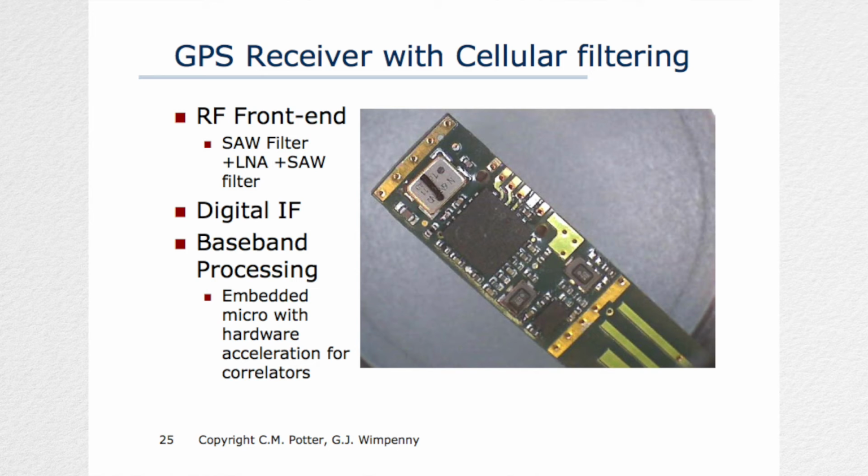There's a serial digital output there. So all of this takes RF in from the satellite and produces a location data stream coming out of it. It simplifies the design task of adding GPS functionality to anything, really. These are 0201 passive components, so you can tell it's quite a tiny module altogether.